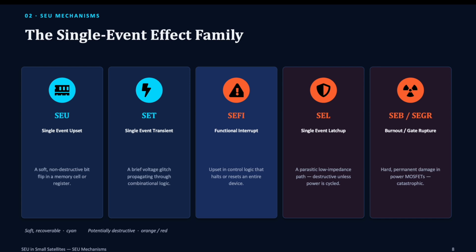The recoverable errors are single event upsets, caused by bit flips in memory or registers; single event transients, caused by a temporary voltage glitch that spreads through combinational logic; and single event functional interrupts, caused by loss in functionality.